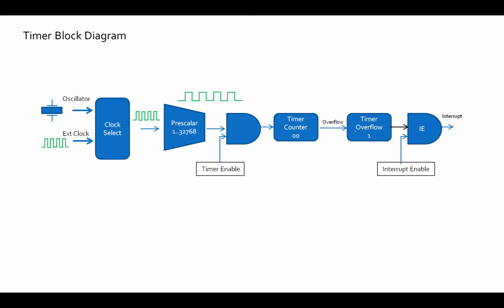So there's several things I have to set here. Clearly, I've got to set timer enable, interrupt enable. I've clearly got to set the prescaler. I had to set this timer here. That's what all the values are. And that's why we need a number of values to make that magic all happen.